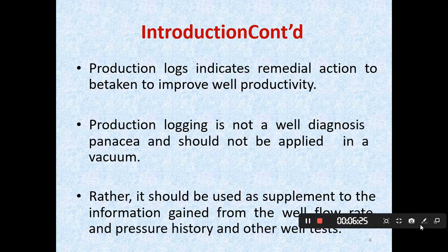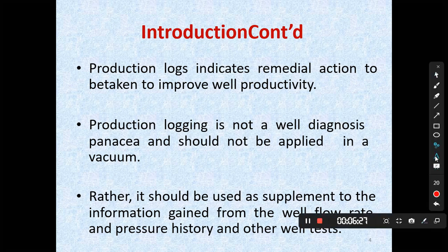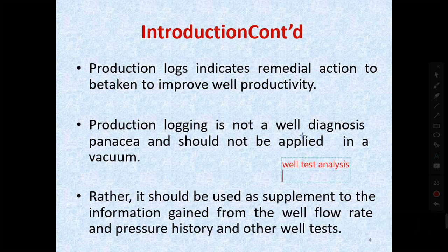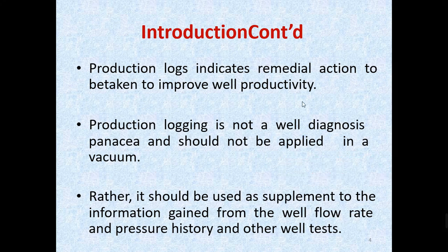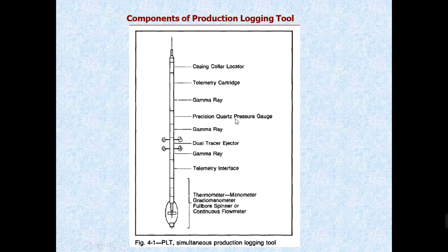Plus, it should not be used alone. You should always accompany it with well test analysis, especially the build-up test, or look at the production history, especially of nearby wells: how much water they are producing, how much oil, or how much gas. Then it will help you to identify what the PLT is doing.